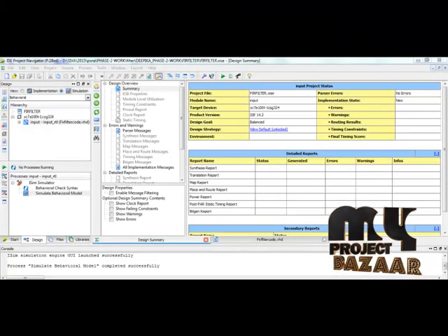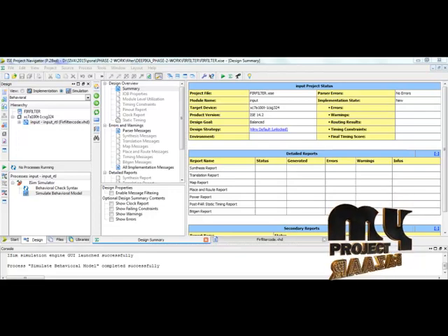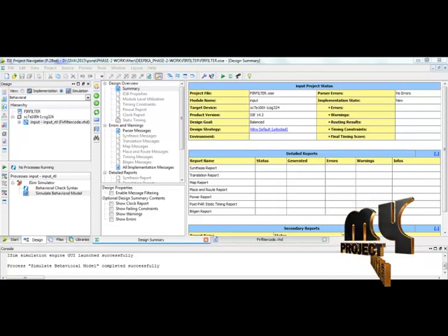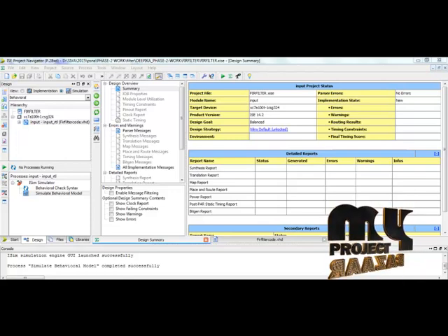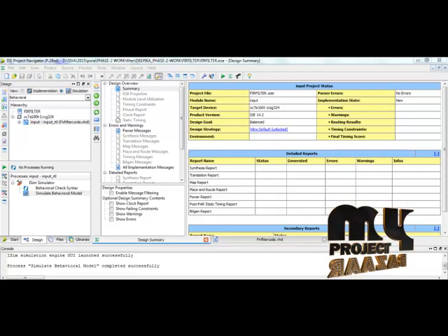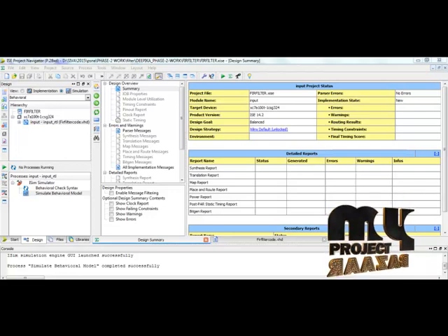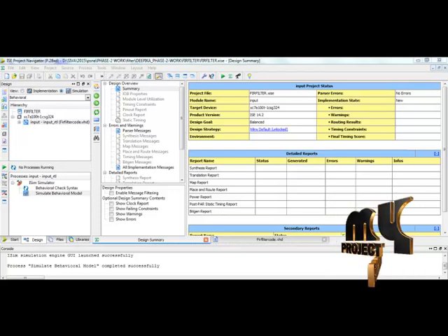Finally, we are going to see the output for our product. We are using Xilinx 14.2 version. For the project, we have to create a new project by clicking on File and New Project. Then a new source is added for the space for the code. The VHDL option is selected, and the storage area is also selected.